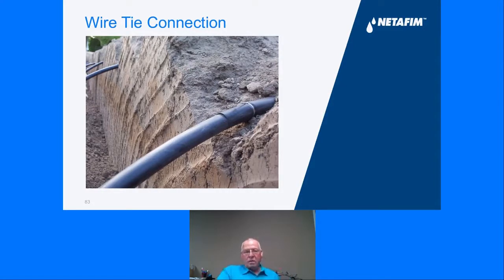Any loose soil underneath these will result in the pipe settling. The sub main is a pipe that the dripper line connects to, and the settling causes the connection to pull out of that rubber grommet in the sub main. If you've got loose dirt underneath that pipe, when you get it connected and the weight of that soil gets on there, and then once that dirt gets wet, it can settle and pull that connection out, and that makes for a very disgruntled customer.